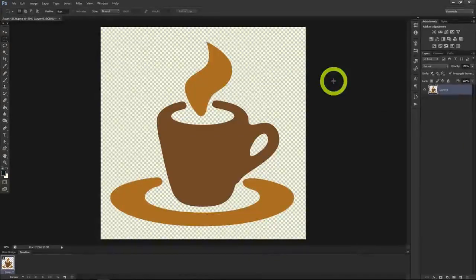Welcome to the fifth in our tutorial series on Photoshop. Here we'll be talking about how to work with layers in our Photoshop document. What are layers? Simply put, layers are the way we can organize our image easily and smartly. With our Photoshop document open, we can see that we already have one layer of the document in place. Over here on the right is our layer setup, and you can see how many layers we have: 1. The hierarchy of layers means how they are stacked in a certain way, and if they're grouped, which they are not.